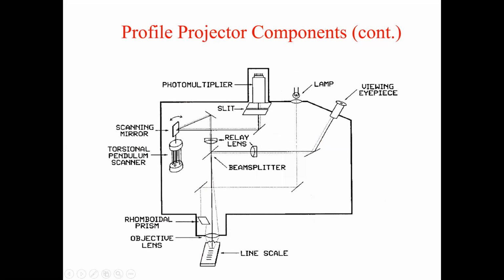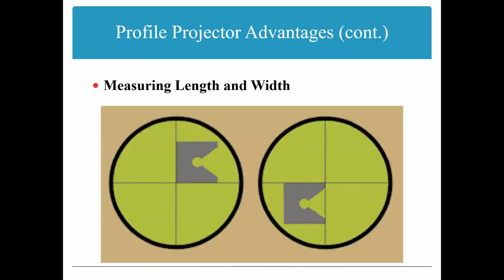Projector advantages, measuring length and width. Profile projectors are generally used for measuring the length and width, linear measurements. We observe here, this is the screen of the profile projector. On the screen, the object image is obtained like this. Here, two engraved lines are there. Those are used as the reference lines.